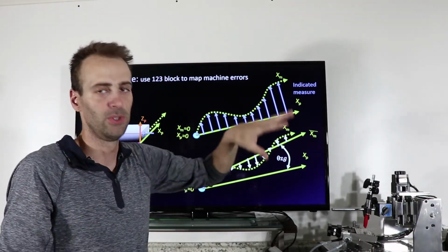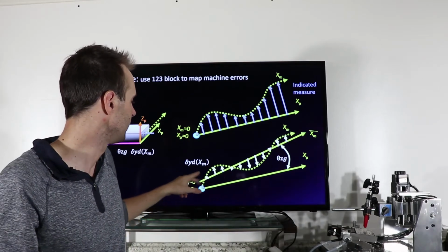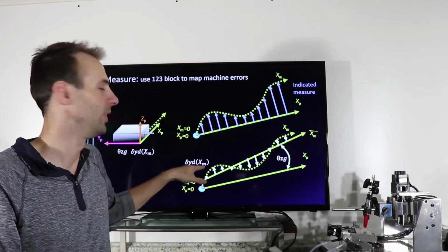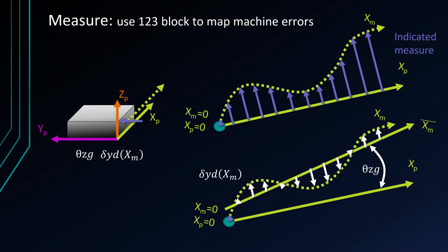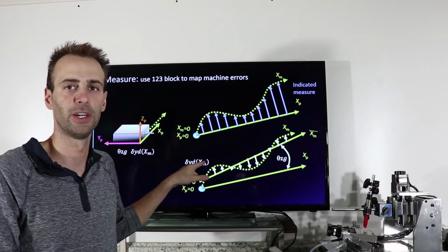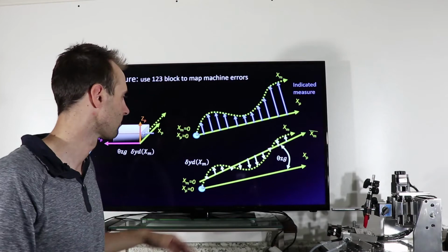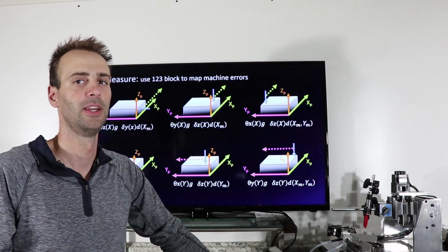But then, if you don't choose to ignore it, now I have the residuals. Okay, then the residuals become my dynamic error as a function of how much I move the x-axis in the y direction. Okay, so this is a linear dynamic error relative to the y direction as a function of my x machine axis. Okay, and then this should make sense as you go through it on your own machine.